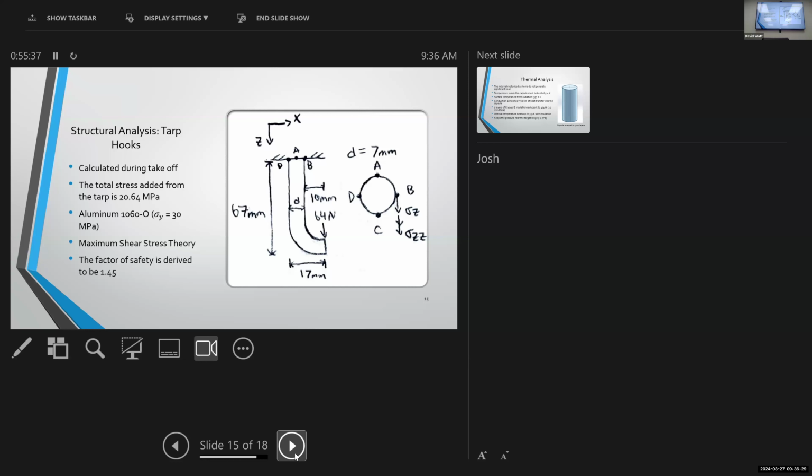I know you do well when you calculate safety factors higher than your target and try to do optimization, but the optimization can be done by reducing size, not by changing to a lower yield strength. First, 1000 series we normally don't use for structure components.